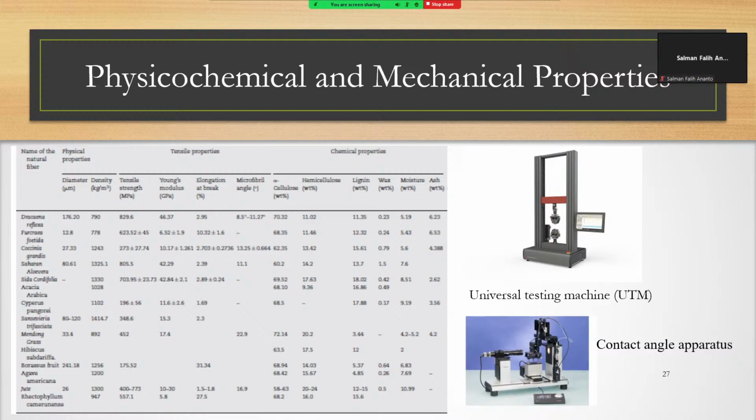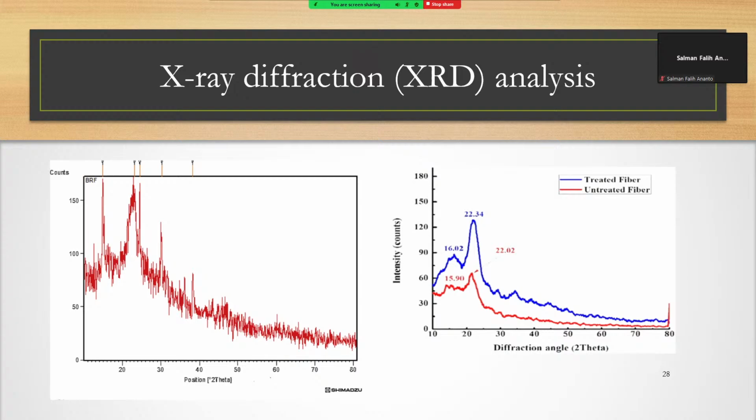Usually, X-ray diffraction allows natural fibers to be scanned in a 2 theta range, where theta is the Bragg angle, varying from 10 degrees to 50 degrees. The right figure shows the X-ray diffractograms of untreated and treated plant fibers. Untreated means raw fibers, and treated means any treatment, here an alkaline treatment. It clearly shows two peaks for each specimen.